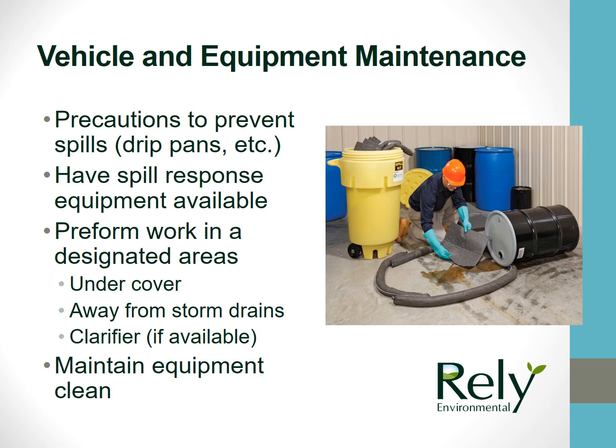In vehicle and equipment maintenance shops, precautions should be taken to prevent spills. Spill response equipment should be available and nearby. Work and maintenance should be performed in a designated area that prevents a possible release. The area should be properly under cover, away from storm drains.